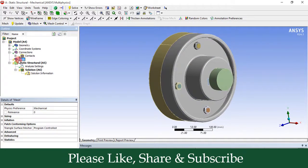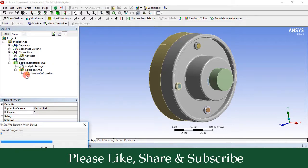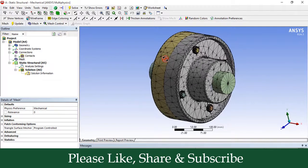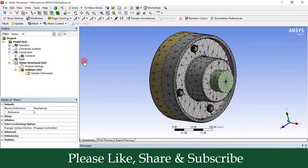Then right click on mesh and click on generate mesh. It will take some time to generate the mesh. By doing this, we are discretizing our model into a number of elements and nodes. So you can see the meshing is completed. Actually, I'm not going for a fine type of mesh, just considering the computing time, to save the computing time.